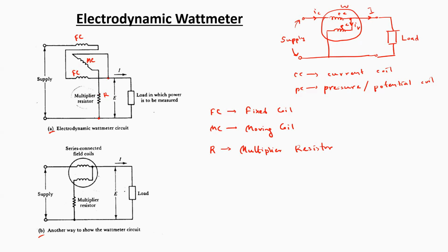If a resistor is connected, it allows the inductive behavior to be mitigated, and if the resistor value is increased, the branch will become as purely resistive as possible, so that the voltage and current through this branch don't have too much lagging or phase difference between them.